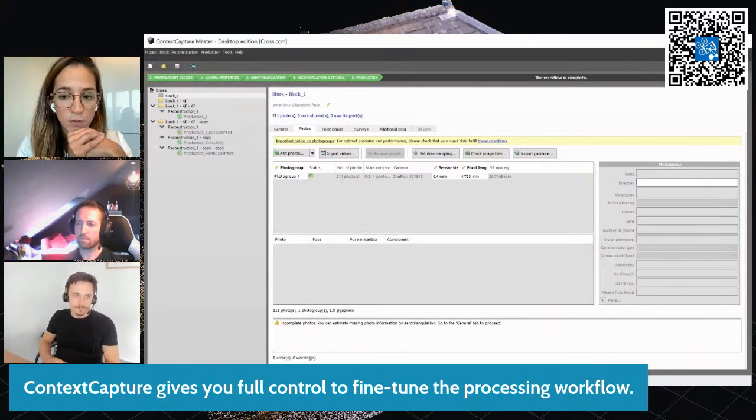He has an Android, and sometimes it's hard to find that information. Is there a workflow to run in ContextCapture to determine the appropriate sensor size and focal length? Or how could he do that? Those two values have to be found somewhere. The rest of the calibration is done during the retriangulation, so all the interior calibration of the camera will be done.